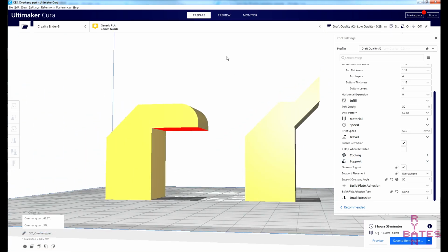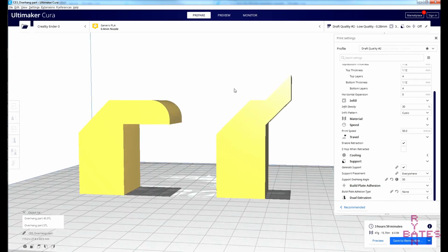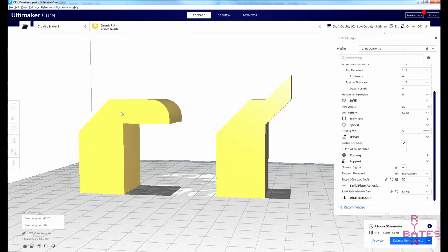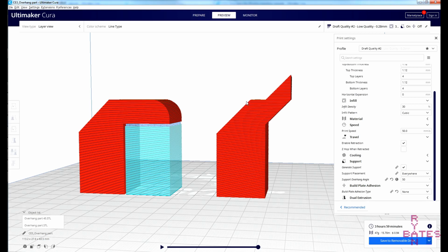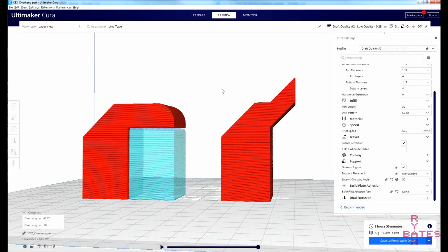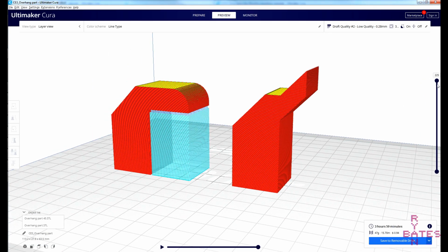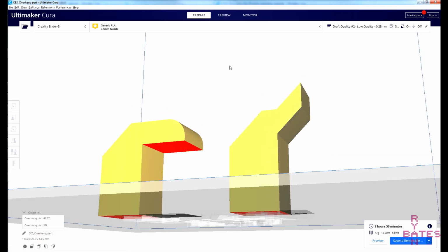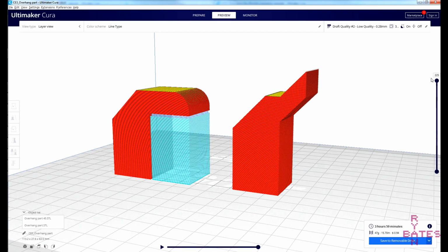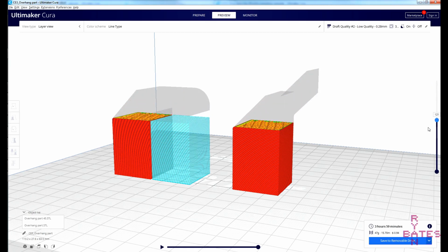Of course, there are exceptions, and this is referred to as a part's overhang. A modest amount of overhang can be printed without support, and this is usually limited to about 45 degrees. Slower printing is better for parts with lots of overhang. Features that exhibit overhang are usually marked in red by the slicer. Adjusting a part's orientation can help minimize the need for support structures, but sometimes supports are inevitable.